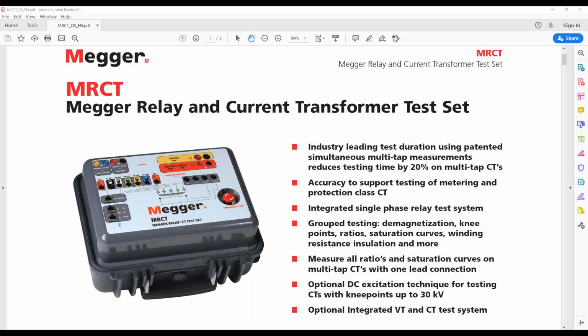But when you're looking at the saturated voltage, you are talking about way on the right hand side of the curve, where the CT is completely saturated. Let me explain a little more. A protection class CT is defined so that you should be able to get a good ratio measurement up to 20 times the rated secondary current, and the error should not exceed 10%.